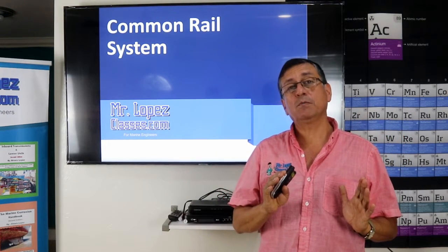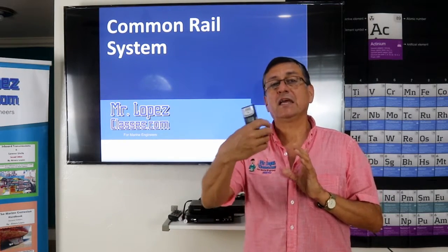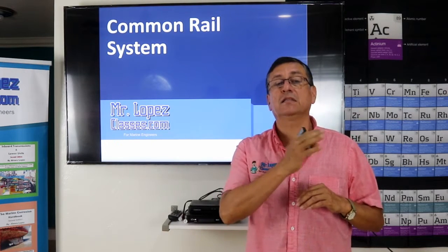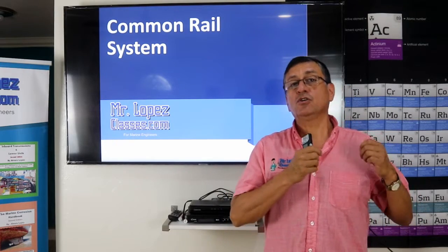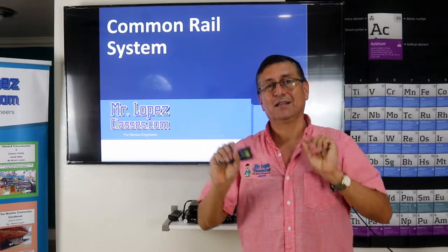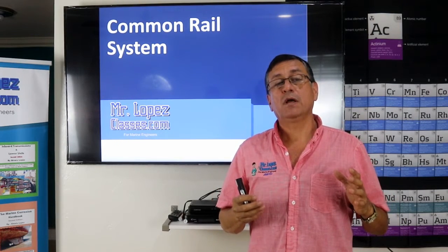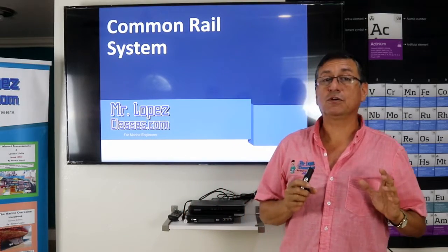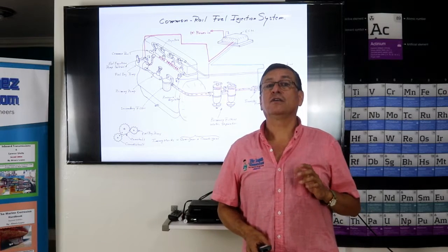If the fuel injection pump is electronic, you can install it at any position of the cam and the crank. It's not necessary to align the timing because the electronic fuel injection pump supplies constant power to the common rail. The common rail is powered from the electronic pump, and the common rail has pressure all the time. For that reason, the pressure regulator on the fuel injection pump is very important.